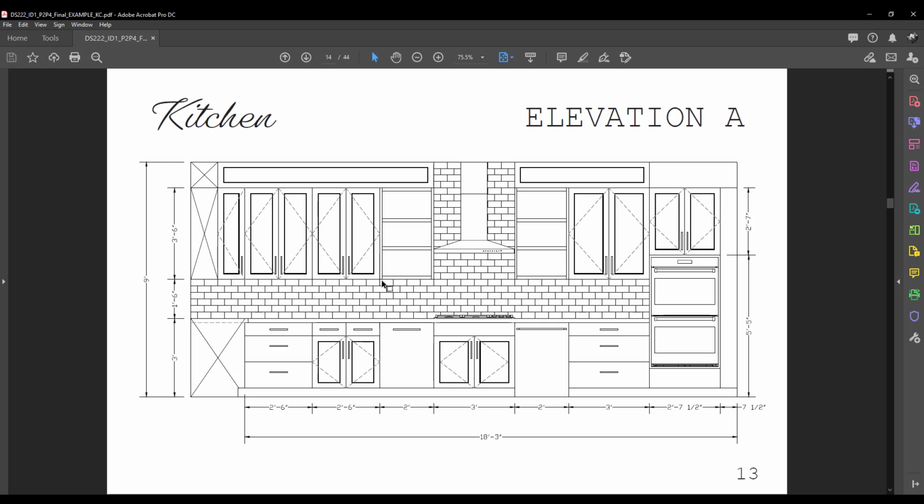Okay, so as you're kind of thinking about creating these views, also think about if you are cutting an elevation through and you have like maybe an L or U-shaped kitchen, that's what you're seeing over here. If you think about this type of drawing where we're actually cutting through the upper and lower cabinets, again thinking back to VCT, and so how does that look, right? We're slicing through. You can either hatch this in or doing a simple X like that works just fine, okay?